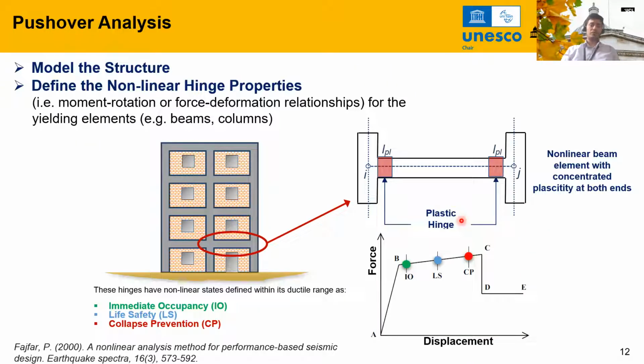So the steps for pushover analysis, just a brief overview. We model the structure using software, for example, SAP2000 or OpenSees or SeismoStruct, or any other available packages. The modeling approach depends on what methods you are using and which software you are using. For example, here we are modeling a reinforced concrete building where we are using a nonlinear beam element with concentrated plasticity at both ends.